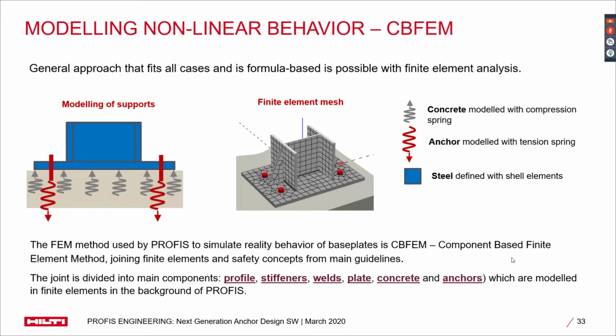And the anchors themselves are modeled as bilinear tension springs. The stiffness of the anchor is unique on a per anchor basis and has been determined through hundreds of Hilti's own internal testing to determine this critical data, as the anchor stiffness has a significant impact on the overall design.